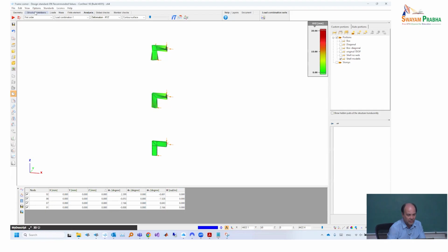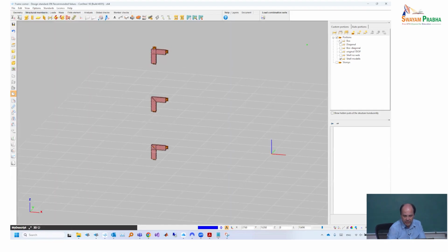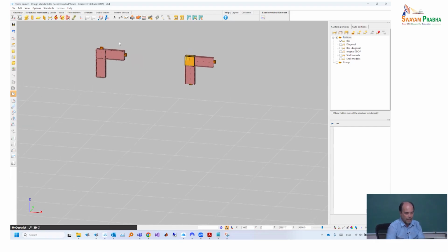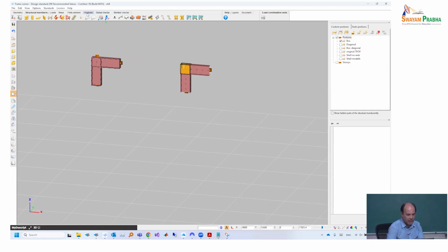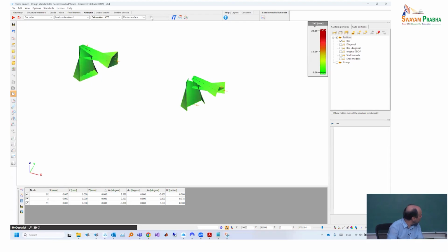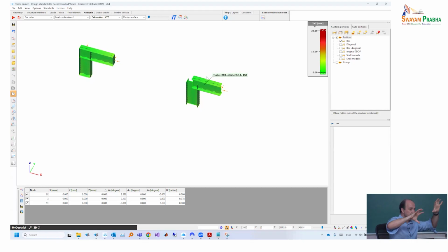And then we found that if we use this yellow representation, which was one of the others, and then we see which was the most critical one, there you see that the left is the shell, the right is our beam. We defined here a certain constraint. We apply some automatic hinges. We don't let the beam element transfer the deformation because it cannot.